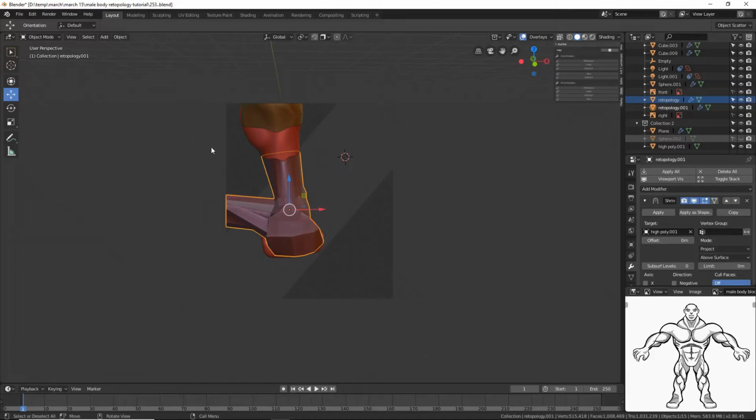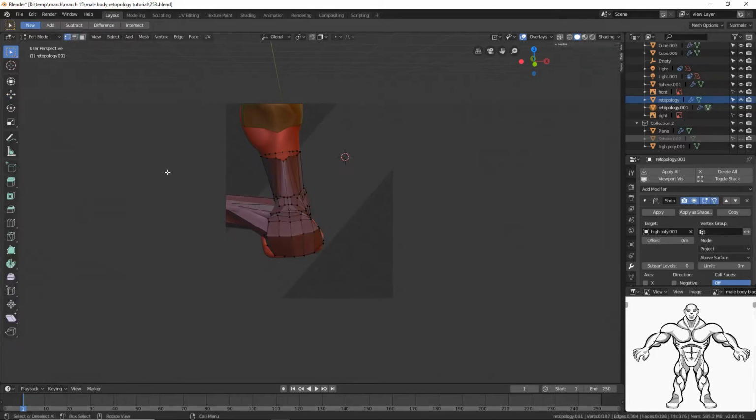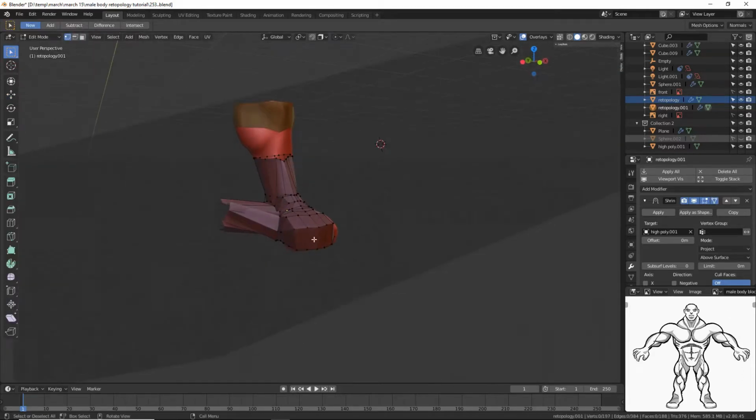We see this right here. We're going to click on what looks like a triangle button here so we can see what we're doing once we go to edit mode. In edit mode, there's not that much geometry here. We're going to hold Control, press R, left click once, left click a second time to lock that in. We're going to make sure we're on vertex select, which we are.